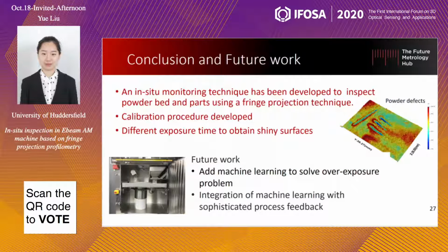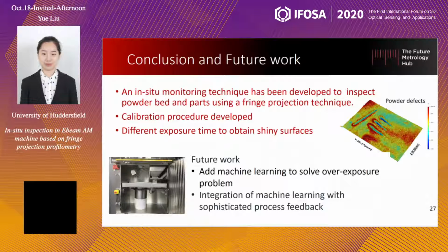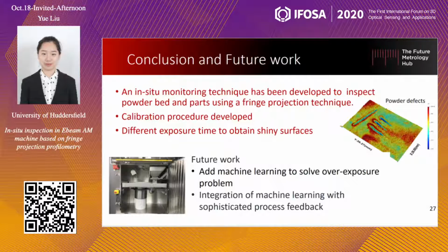A brief conclusion and future work. An in situ monitoring technique has been developed to inspect the powder bed and parts using a fringe projection technique, and a calibration procedure developed and try to use different exposure times to obtain shiny surfaces. And in the future, we want to add machine learning to solve the exposure problem, and integration of machine learning with